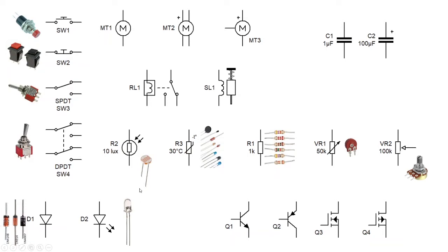LEDs, they are actually diodes as well, so they only work in one direction too. Now you might notice one of the feet, one of the little legs is shorter than the other one, or you might find there's a little notch across this wider bit, this flange. So a little notch chipped off on the negative side, just to tell you, okay, flat, negative. So that bar there corresponds to that notch. That is the way to connect them. They won't work the other way around. So you need to make sure they go one way round. So LEDs.